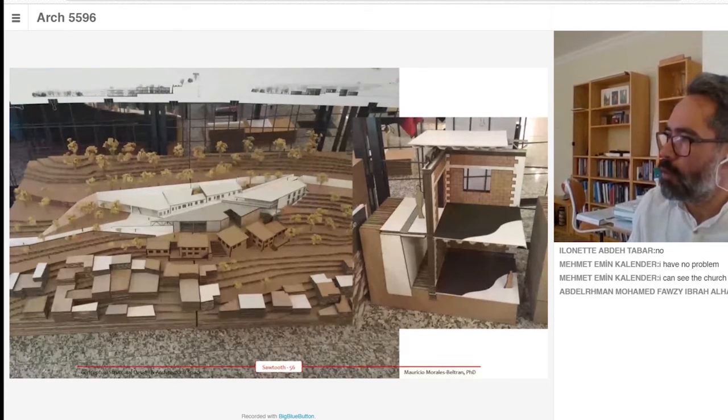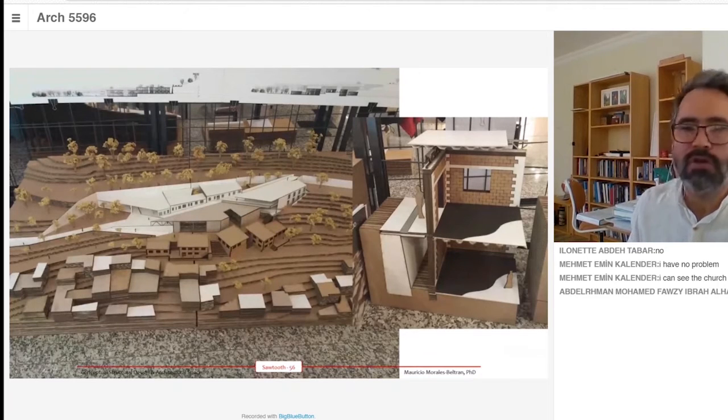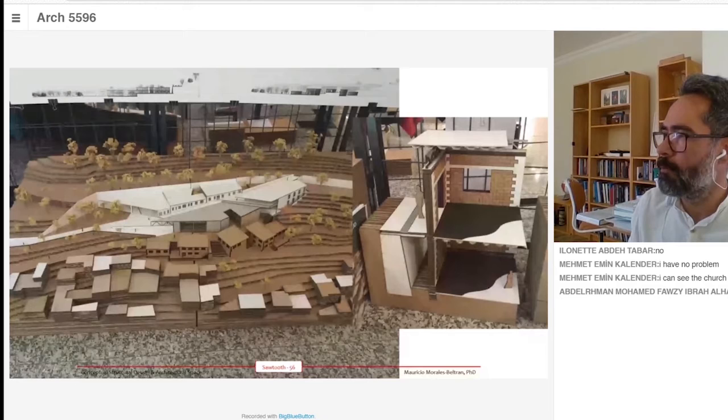Remember, if you look here to the right, you will see I think it's a block wall or maybe bricks, and you see these very weird teeth here. Well, this is a technique to make the masonry element be part of the wall. So this wall is structural and works as one thing, which is something I was discussing at the beginning.